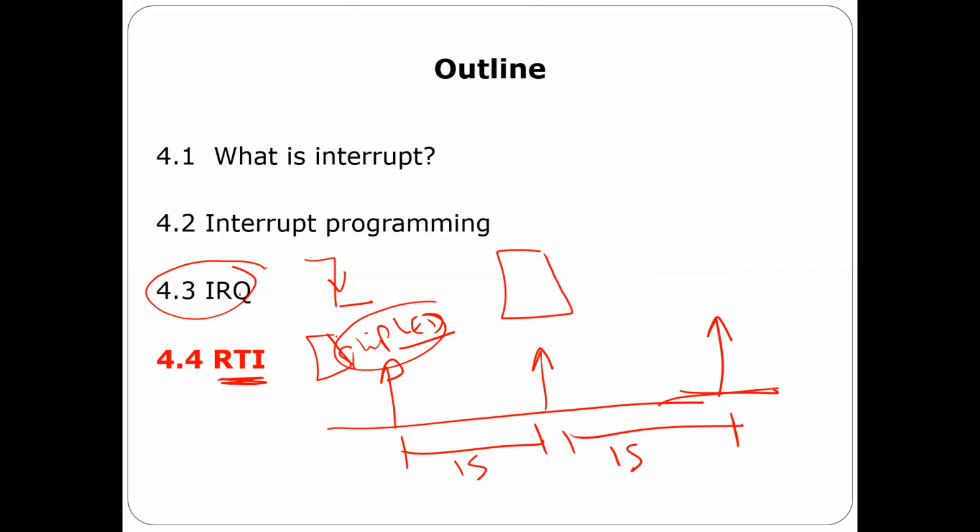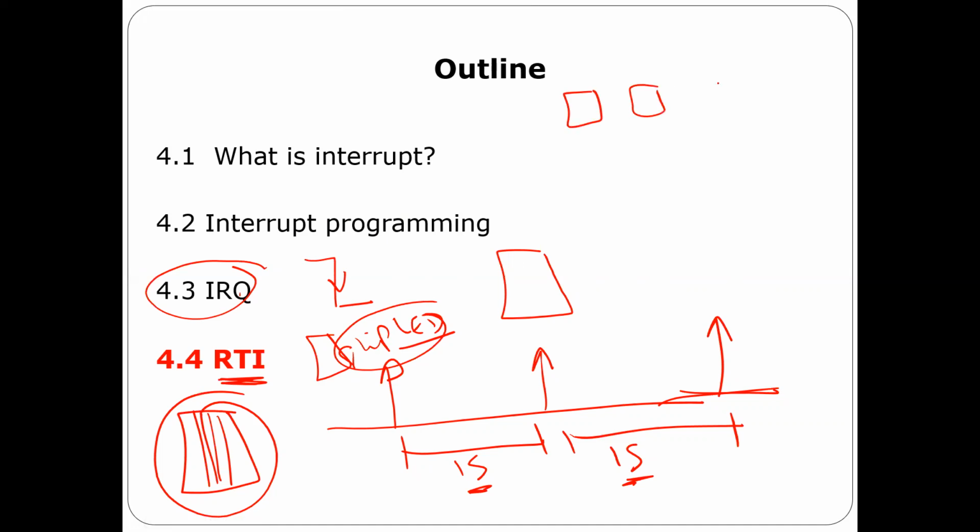When I say I'm going to trigger interrupts every 1 second, what I mean is that you are going to execute the RTI subroutine every 1 second, right? Because this is how interrupts work: when you trigger an interrupt, you execute the subroutine. So that means I have a code, and I am sure I'm going to run this code every fixed time, for example every 1 second. This way, I can make a flashing LED. Is that okay, guys? Another thing, that's what we're going to see right now, so don't worry. You remember the idea of time multiplexing of the 7 segment.